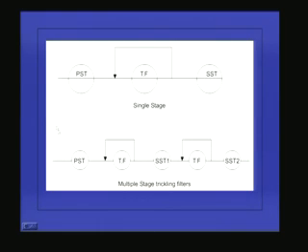So this is how the recirculation works. I told you in a trickling filter we recirculate the water. So we will be having a primary sedimentation tank. This is essential. The reason is the wastewater will be having so much suspended solids. If you don't remove the suspended solids, they will go to the trickling filter and get accumulated in the pores of the trickling filter, and clogging of the trickling filter can take place. So that's why it is always advisable to have a primary sedimentation tank before the trickling filter.